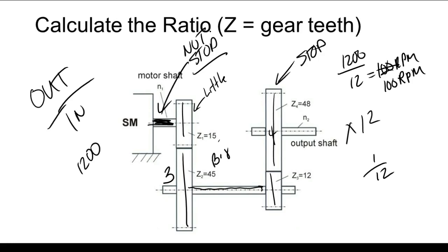Of course, in a straight shift, you use it when you're standing at a red light. You got to have your clutch in. Why? You understand that? And then, of course, it allows us to shift between gears in the straight shift without stopping the prime mover, which is pretty neat.